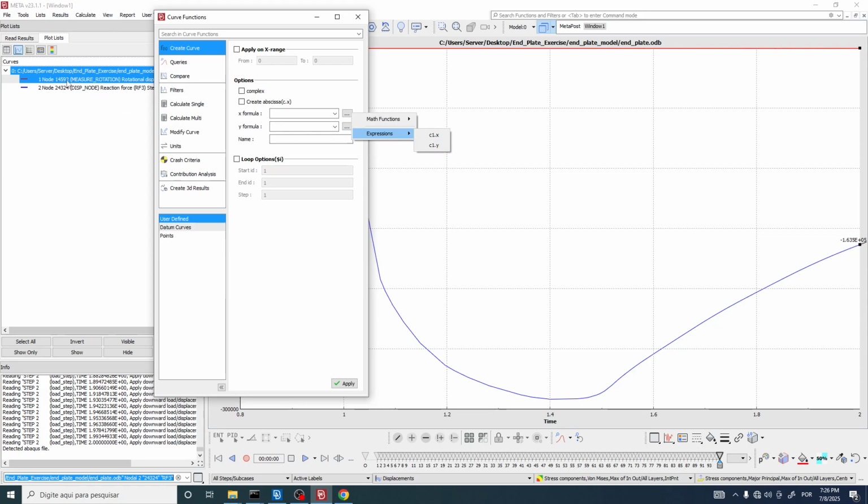Well, I double clicked on this curve because now we have this curve selected, and then the expressions that appear here are related to this curve, which has ID equals 1. So that's why we have C1. Okay, you see the ID is here where my mouse is positioned. So in the x-axis, I want to put C1.y, because C1.y is going to contain the information about rotation.